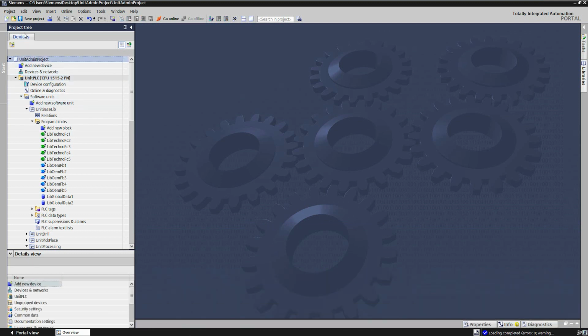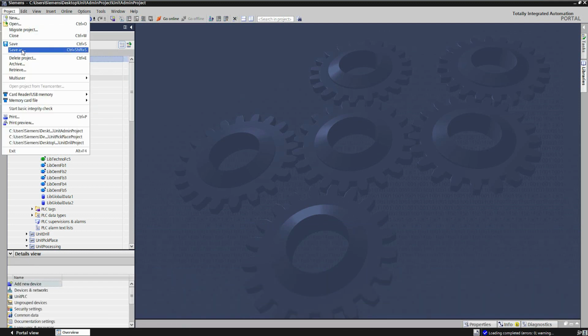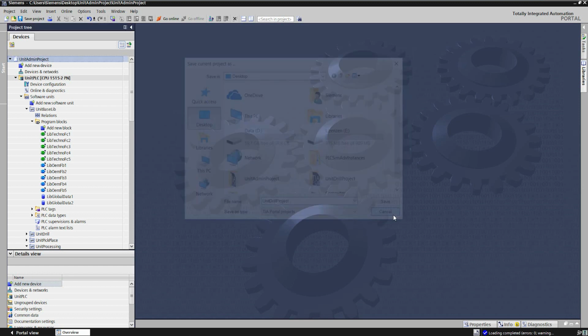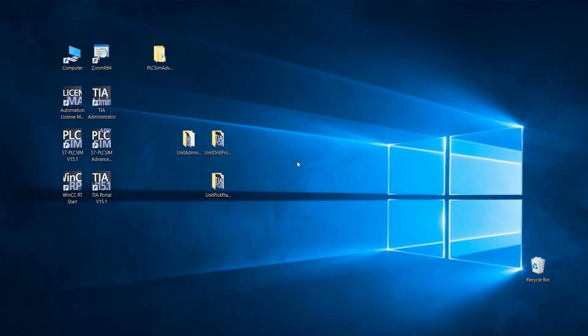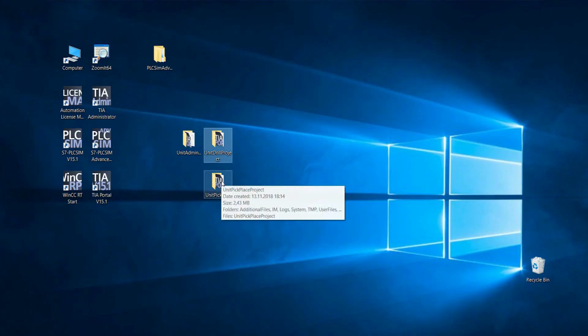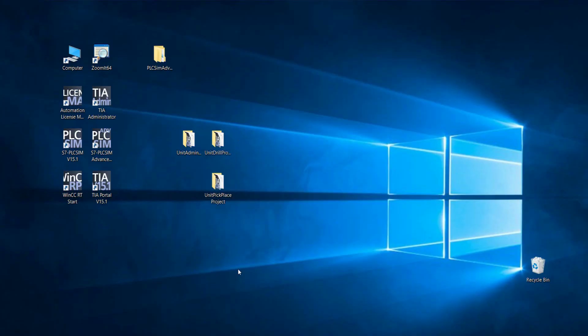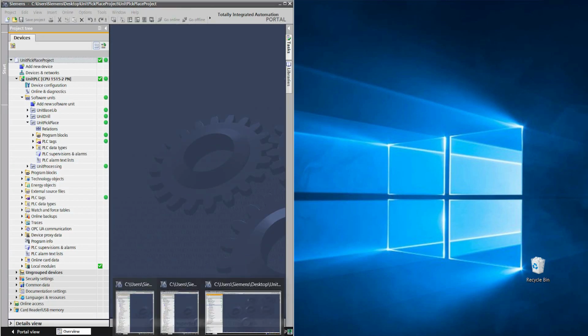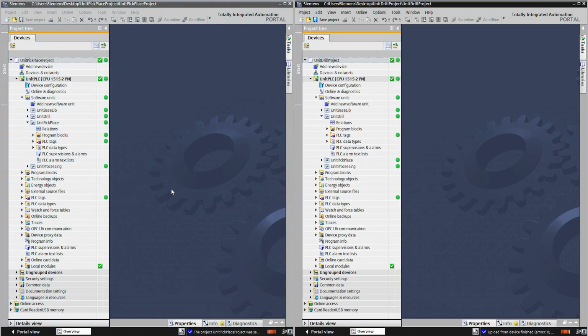Following by distributing project copies to the colleagues from the commissioning team. So for a successful teamwork, it's important to also split the team responsibilities according to the application unit distribution. Think about who should commission what unit, maybe even define your units based on that. Thus, all colleagues separately go online to the PLC with their project copy in order to work on the unit further development. In doing so, they also can test, change and optimize the application within their scope of responsibility, and finally delta download their unit to the PLC.